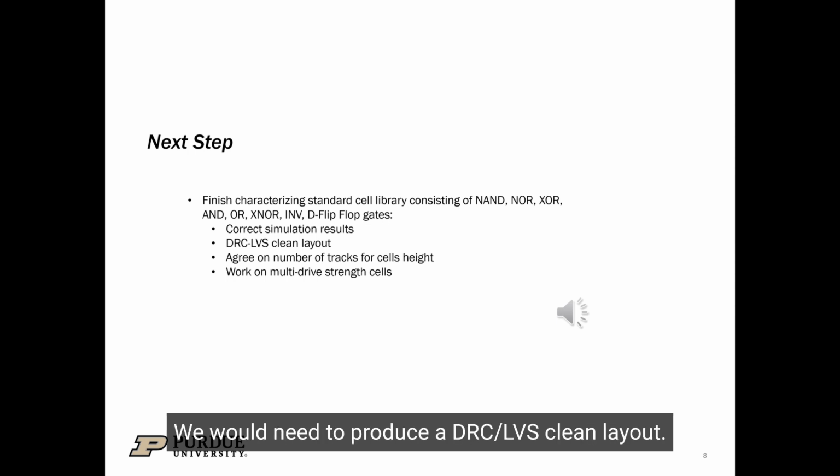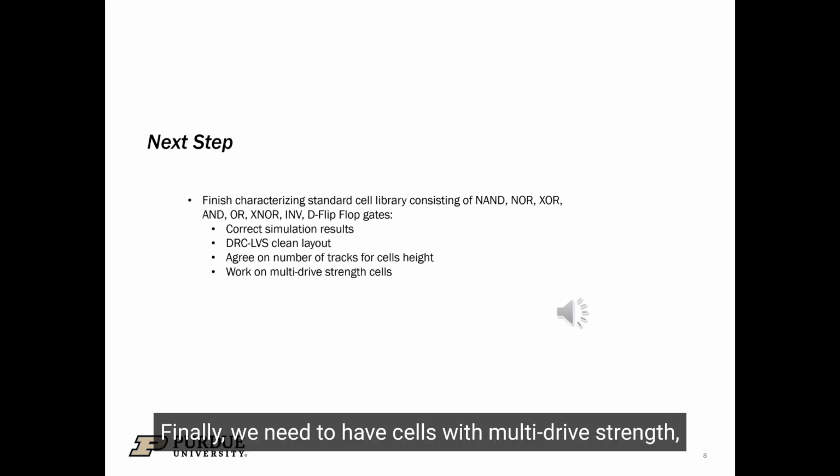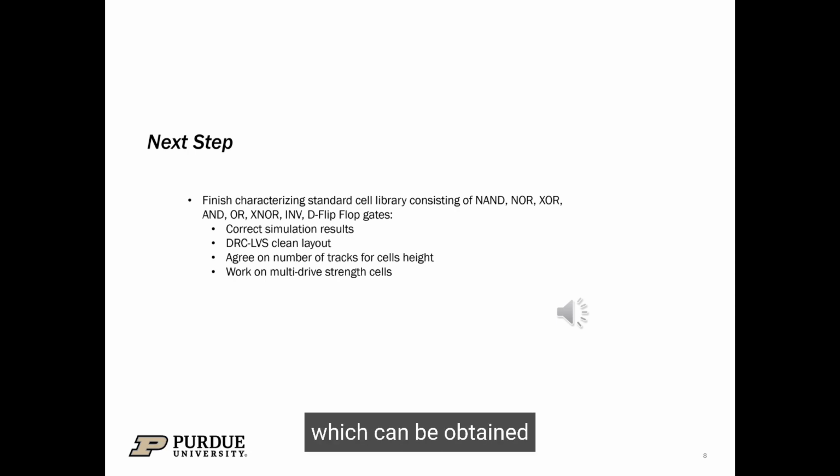We will need to produce a DRC and LVS clean layout, and we will need to agree on the number of tracks for the cell's height, since all cells need to have the same height. Finally, we need to have cells with multi-drive strength. This can be obtained by adjusting the